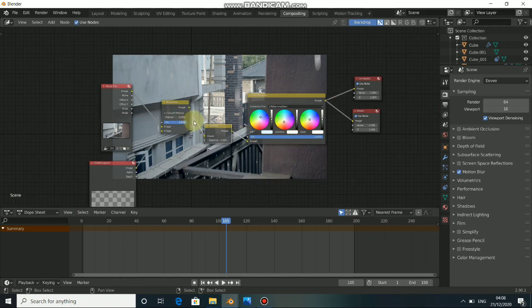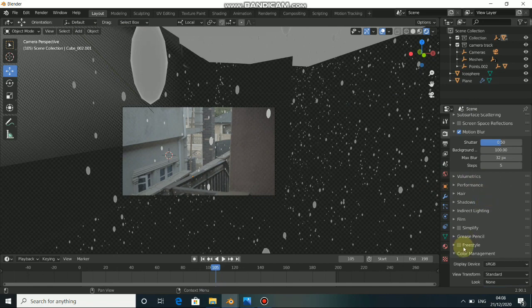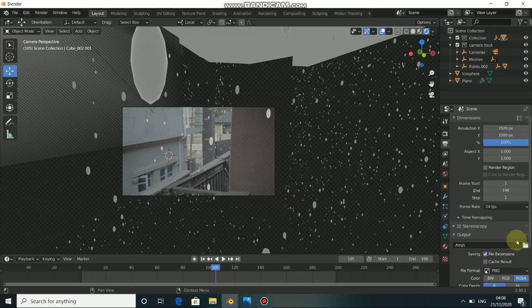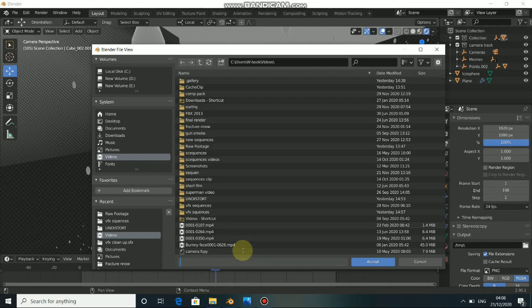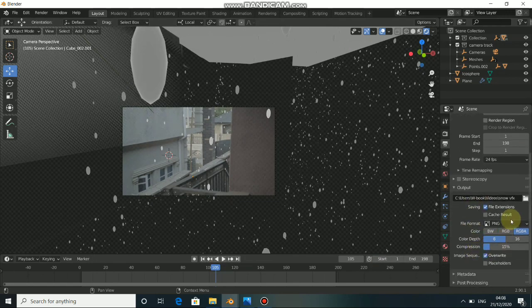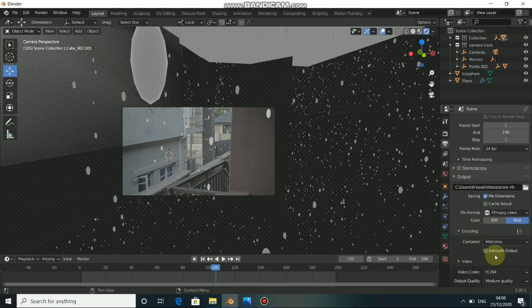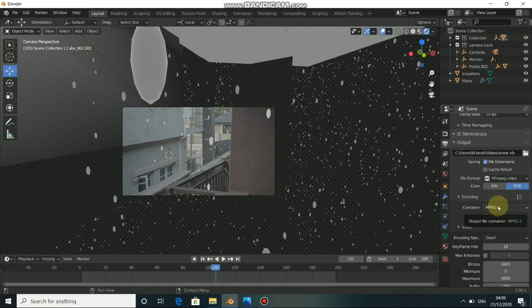So when you give this final render, now you have your animation. And to do this, click here, click on output. Now click here to add an output to this. You can just click the movie, do an output, small effects. Now you can come down, click edit this and change it to video. Come down to the encoding, now change it to MPEG-4 and MP4. Now select. Now we have the MPEG-4 MP4 quality of this.